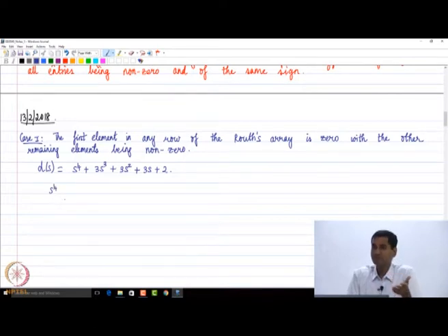If you want to figure out the distribution of roots, you can continue even if that necessary condition is not satisfied. That is the necessary condition for stability, once you look at the closed loop characteristic polynomial. But in general, Routh's criteria can be used to figure out the distribution of roots of a given polynomial, so you can continue even if some entries are negative. Anyway, let's continue and construct the Routh's array.